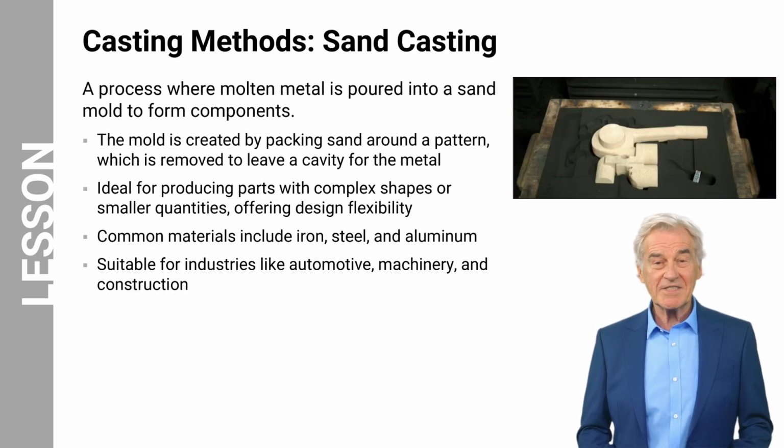Sand casting is a process where molten metal is poured into a sand mold to form components. The process begins with creating the mold by carefully packing sand around a pattern, which is then removed to leave a cavity that will be filled with molten metal.